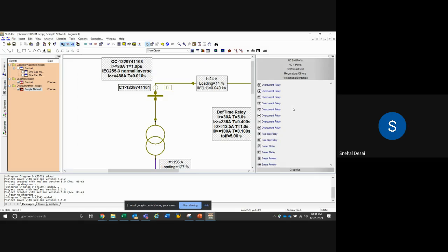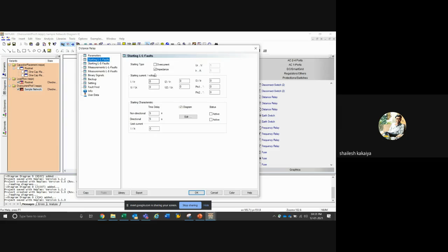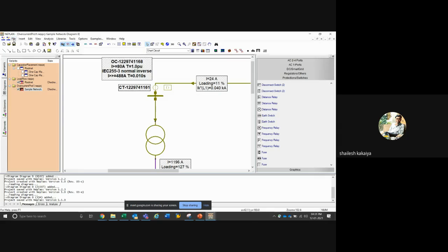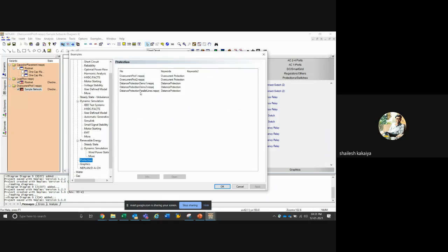Distance protection? Distance protection, yes. Distance protection comes up in here. Z, it comes up here. So here it is quite elaborate modeling. There again, you can take from the libraries, and it has a polygon or circle settings for the characteristics, and then the different characteristics for the things defined here. This I have an example. I can show you that. Protection, distance protection.